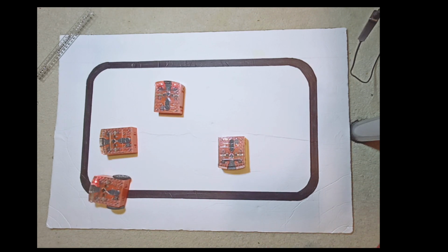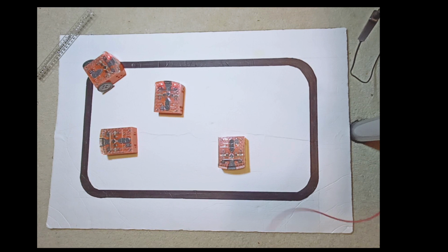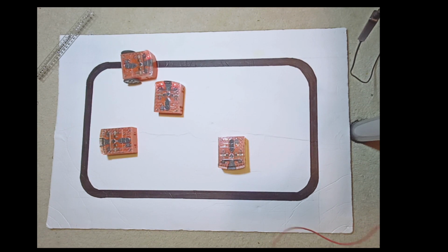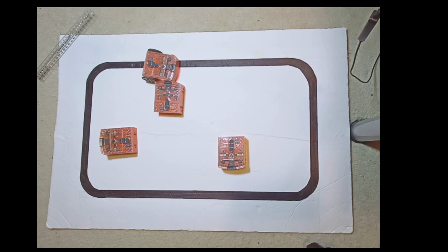So as you can see, those 2 LED lights are being used for indication that the train is being summoned at that station, and when the train arrives at that station, the lights turn off. The collision detection tells the Edison robot that the train has arrived, and the infrared signal sent to the train tells it to stop, and it does not need to continue any more for that specific station.